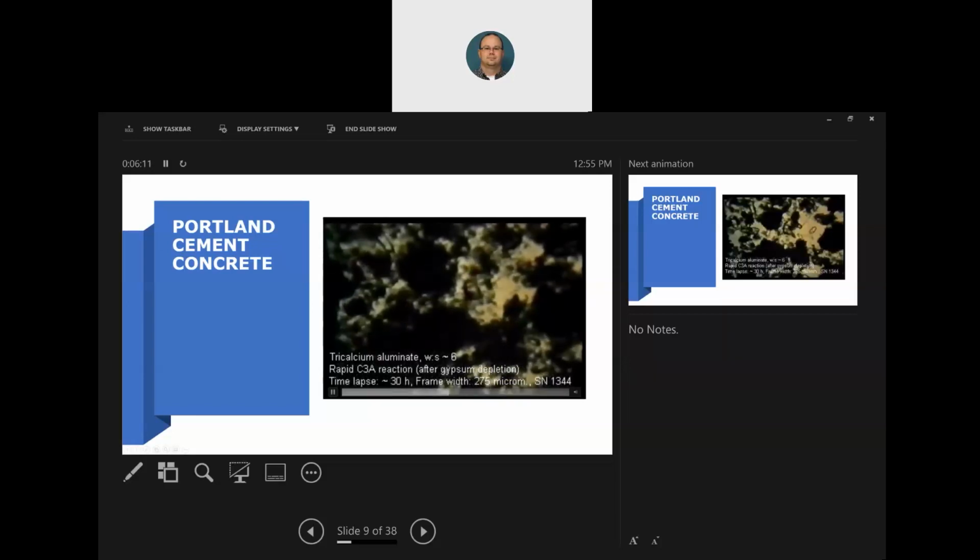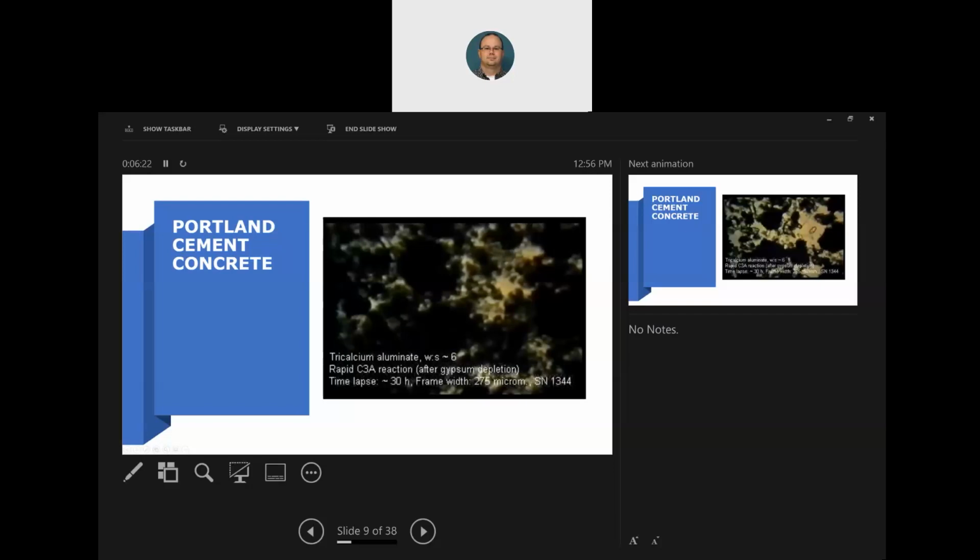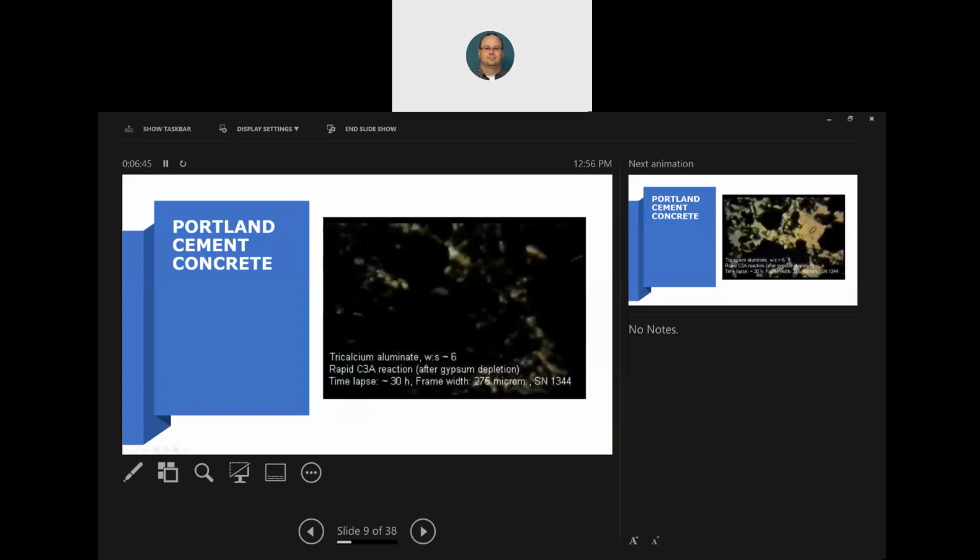I thought this was kind of a neat little video. So this is 30 hours. Look how small that is: 0.275 microns. So that's really small. As you can see, the water is disappearing. It's hydrating into the cement. It's a chemical reaction. So over time, this is what you want your cement to look like.